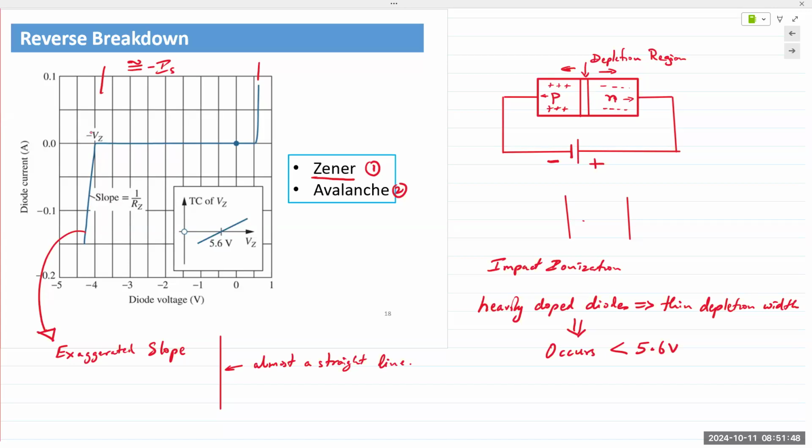Yes. Diodes will still. The question being asked is, if we are operating a diode in the reverse bias, would it still work in the forward bias? The answer is yes, unless the thermal dissipation is so much that we destroyed it. But again, there are diodes which are specially formulated to work in the reverse bias, which is the Zener diodes. And that is one of the experiments we'll perform in lab 4, I believe.